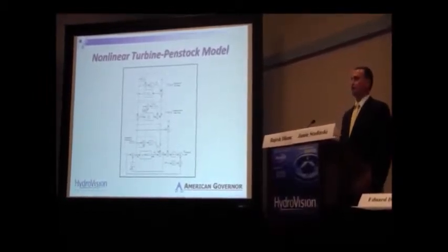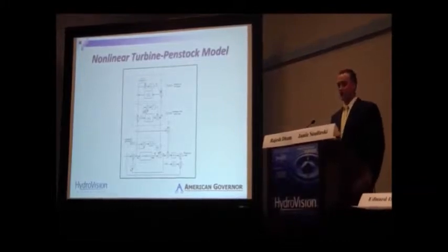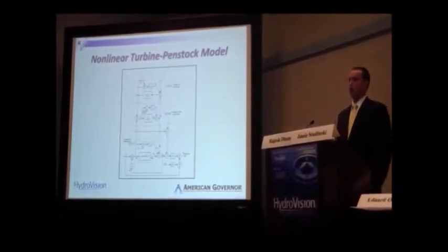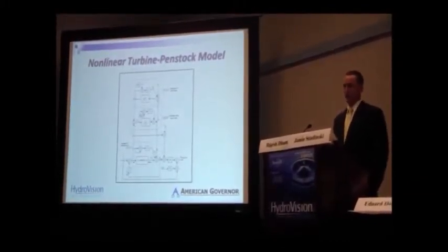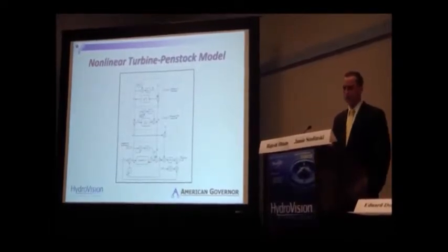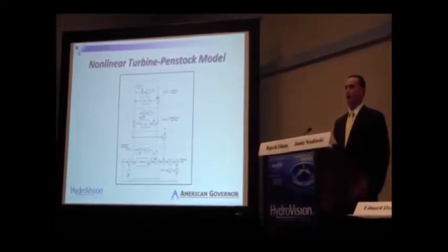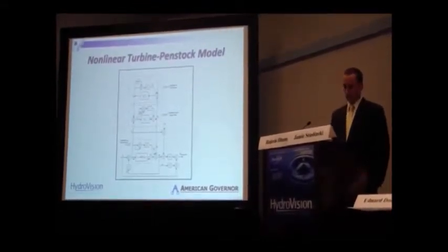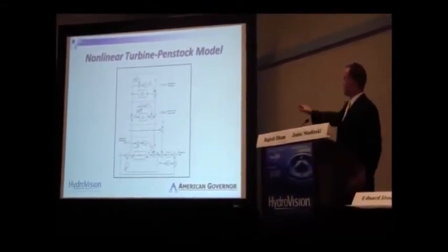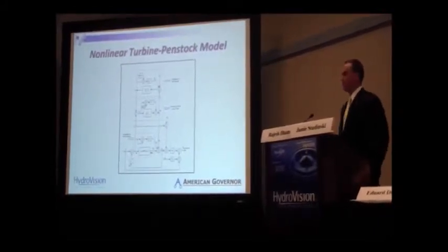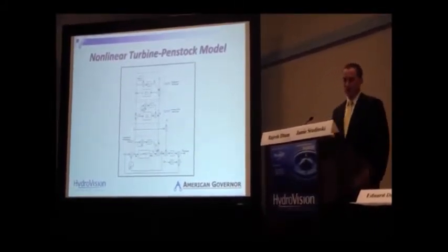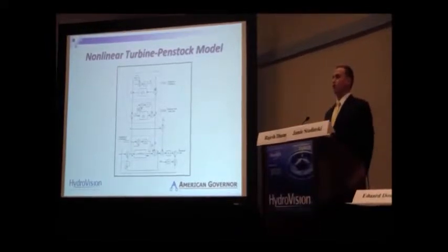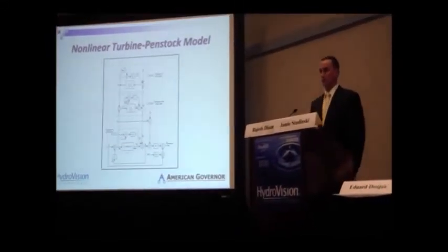Mainly, the consideration is that upstream of the surge tank, we can consider a water column flowing through that main feeder tunnel to be an inelastic water column, meaning that pressure fluctuations really aren't affecting the flow or the level of that water because we're sort of buffering those through a surge tank. Of course, then, in the middle section of this math model, we have dynamics accounting for the surge tank itself and how that affects water flow through the unit and, in turn, the speed of the unit.